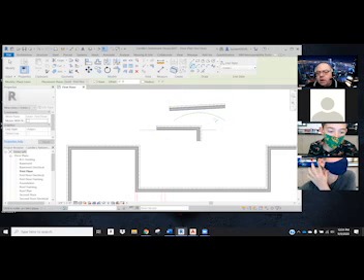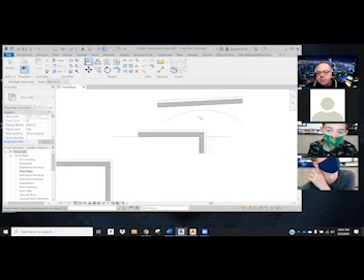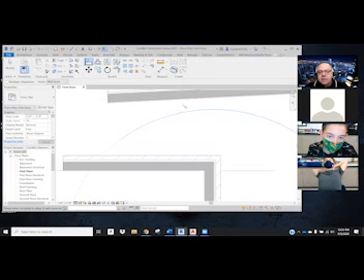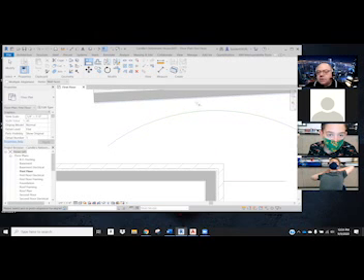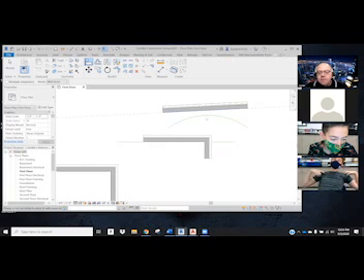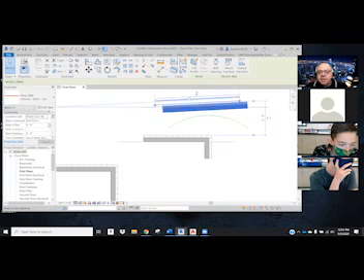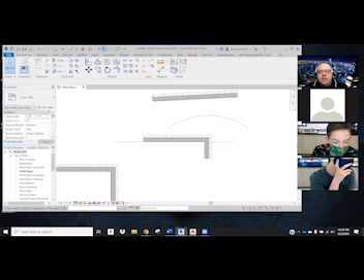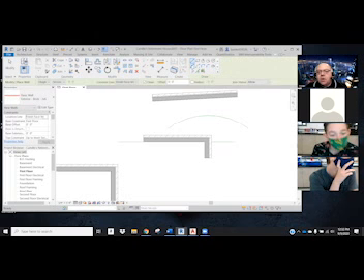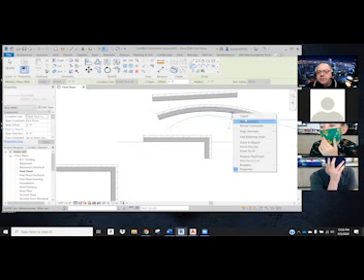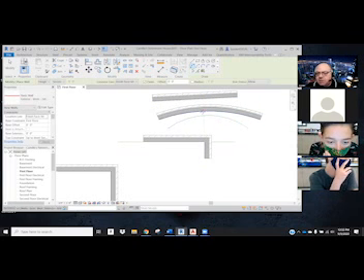But if I have a straight wall and an arc, and I use my align tool, if I select the arc and then, oh, come on, you want to do it. Those two aren't going to work because it's straight, right? But Sam's trying to draw his wall, so I can't bend the property here. I have to use a radial wall. So I'm just going to move this for just a minute, and bring another wall in here. So Sam has a wall he's trying to work out. He puts in a radius to it, but it doesn't match the radius he wants. So a straight wall won't work. So don't do straight walls.